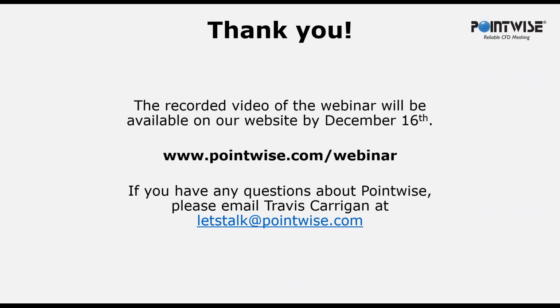It's more of a modal command, and what happens is when you enter grid distribute, it's almost like you enter a bit of a sandbox, I guess you could say. So if I go in there and I select 10 different spacing constraints around the perimeter of a domain, and I change them and then apply that, I will have one domain update for the 10 spacing changes. If I contrast that to doing the same thing with the toolbar version, I would have gotten 10 different domain updates for each one of those spacing constraint updates.